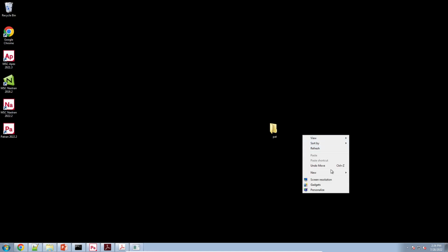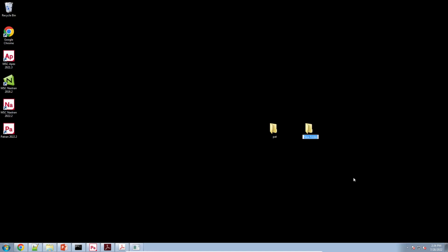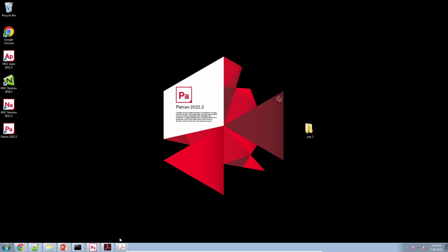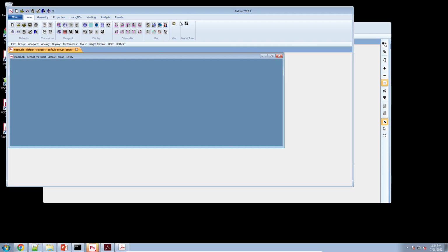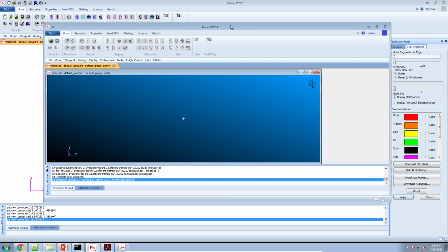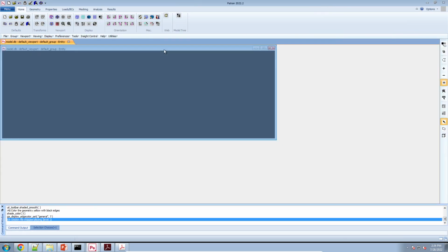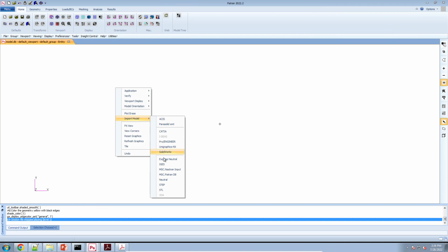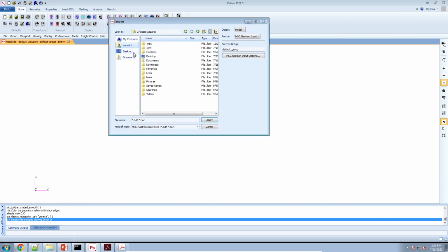And always open Patran and make sure that things look okay. It's very easy to create a cross section that has a few issues like this cross section. So I always recommend doing this check. So let me go ahead and show you what the process is like here. Let me go ahead and import this new bulk data file.